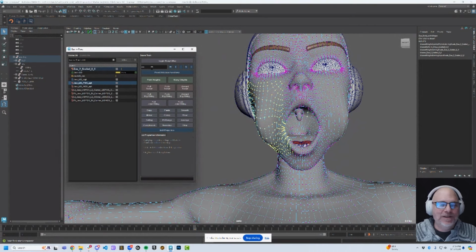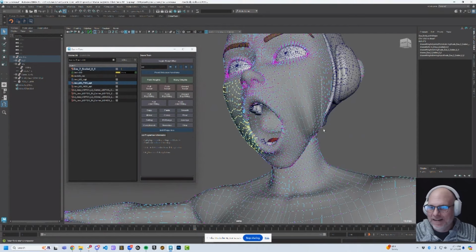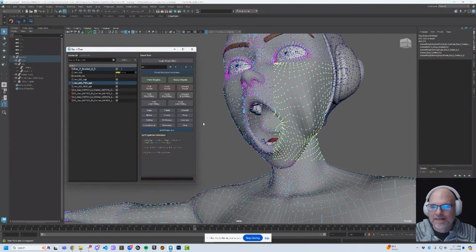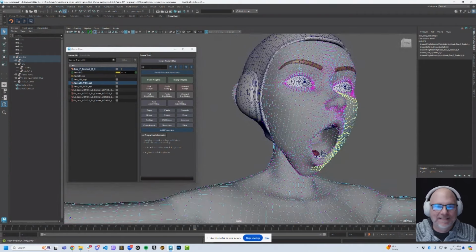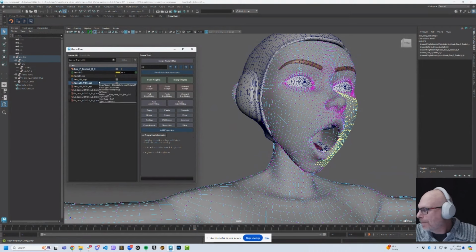And I can come here too, and I can say, hey, I want to equal it to 0 and just subtract out the sculpt. Because just in case anybody's wondering, how is this different from just smoothing out a shape with an averaging? It's not. It's actually taking the vector those points are moving in and applying it to vertices around it. It's doing something that other sculpt tools don't do. If you're doing it in the modeling phase, it's exactly the same.